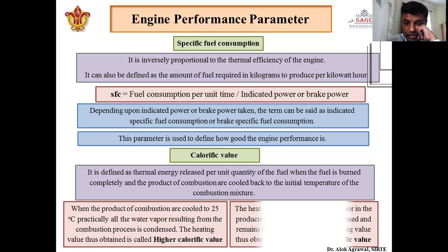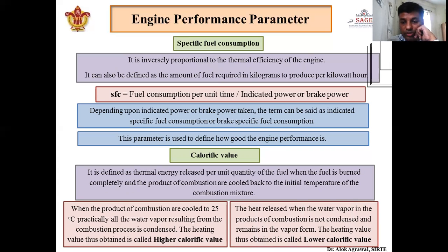And if we do not bring the products of combustion back to the initial temperature, then the amount of energy released is called lower calorific value. Generally we deal with lower calorific value. Higher calorific value is mainly not of practical use because we are not very much concerned about bringing the temperature of the exhaust gas to the normal temperature.